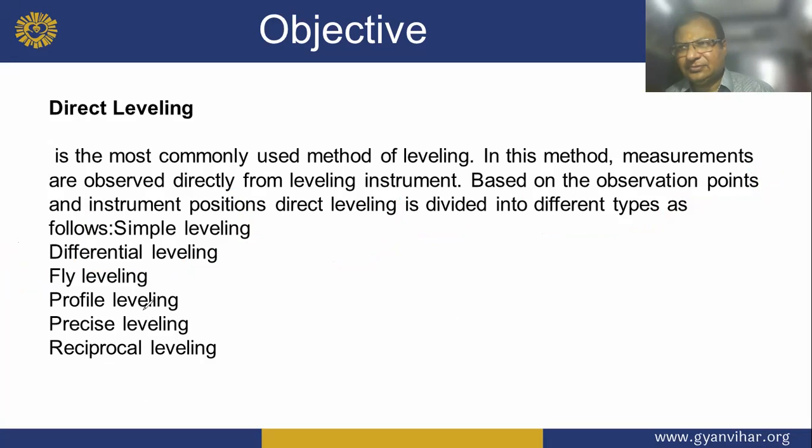Next, profile leveling. Dear boys, if you want only the profile of the natural surface level, then with the same apparatus you can do profile leveling. And precise leveling: if there is any big object, you will take many changing points and do precise leveling. And if your target is many things, then you can take reciprocal leveling.